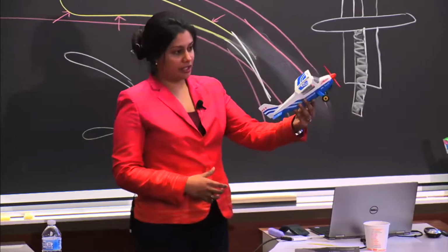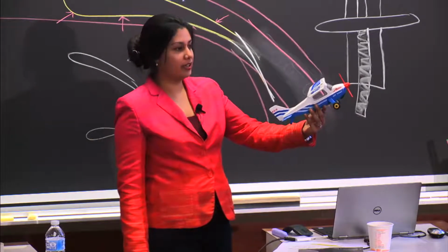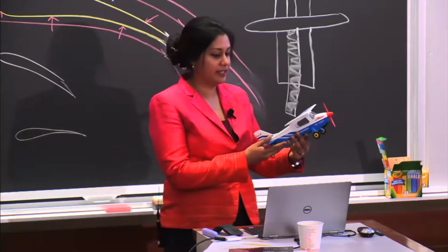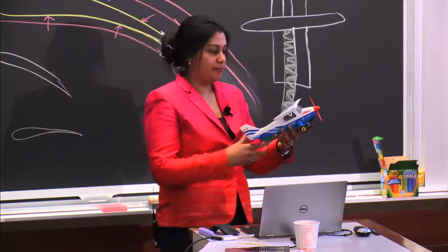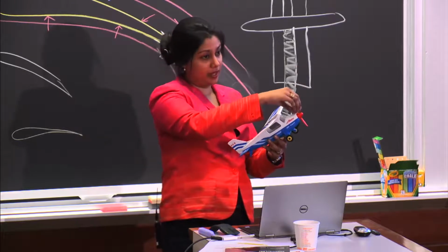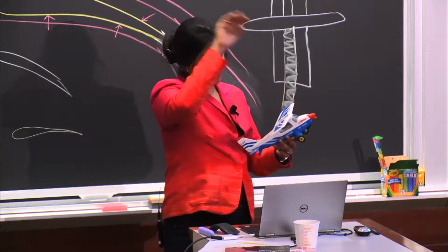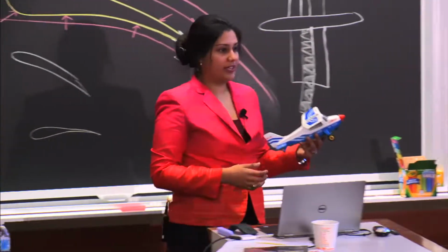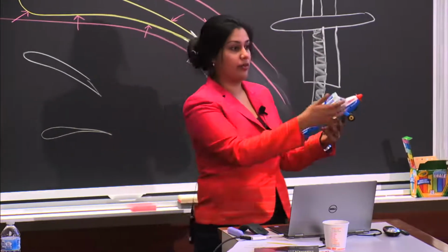So if you're pitched up and you have a high angle of attack and you're either climbing or in slow flight, you have this tendency where, because you're angled to the wind, the right propeller blade, which is descending, is cutting into the air that's coming in. So it's actually generating more thrust.